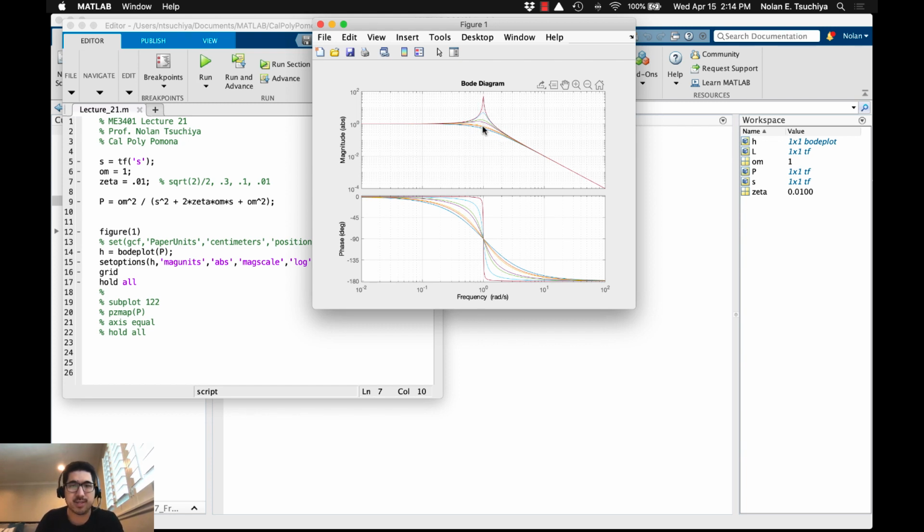Okay, and so for very, very small values of zeta, it can be a bit concerning, because if you were to excite the system at that resonant frequency, right at that peak, you can see that the value is very large, right? It's 36.5 times larger than the input value. Okay, so this is one reason why the Tacoma Narrows Bridge video is such a prominent example of resonance, is because you can really see how the input sine wave has really been amplified in the output, and that's what caused the destruction of that bridge.